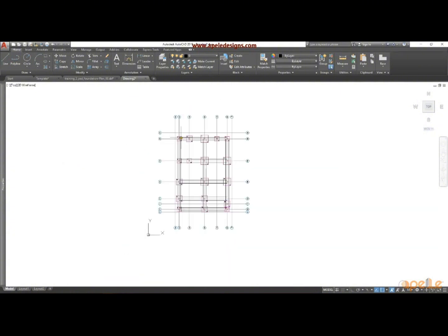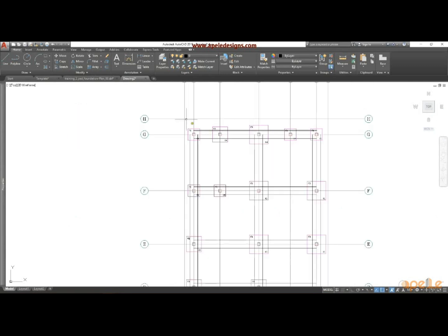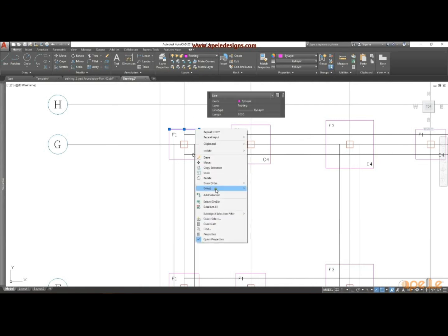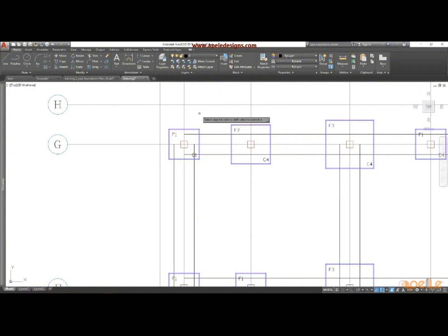Okay. Now it will be to trim the lines that go through the pad base. To do this, just pick on the pad base. Select, right click, select similar. Here you hit on trim. After hitting on trim, you pick the elements you want to delete. I think I'll delete this one, delete this. I'll keep doing it continuously until I'm done. Just watch it.